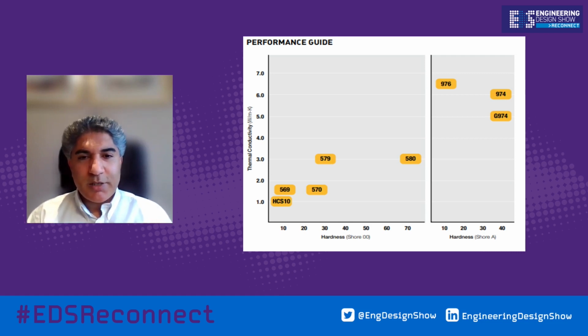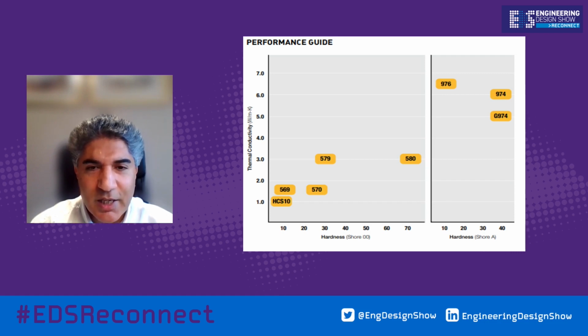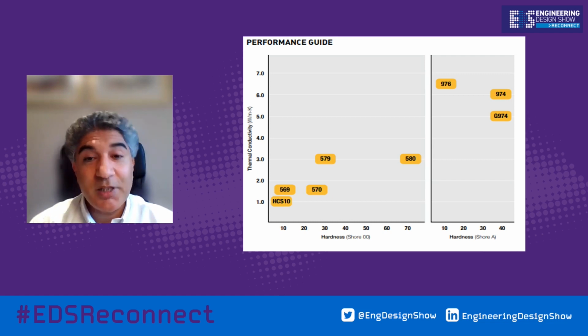The aluminium is also used to give it some rigidity, and also to carry the pressure sensitive adhesive. So if you want a pressure sensitive adhesive gap pad, you start by putting an A in front of the part number. As you see from this segment, the higher the shore hardness, the higher the thermal conductivity, up to 6.5. Within the Chomerics range, they do have a pad 60 and a pad 30, which are relatively new materials. Pad 60 is 6 Watt Kelvin, and pad 30 is supposed to be 3 Watt Kelvin, but it's actually 3.2 Watt Kelvin.